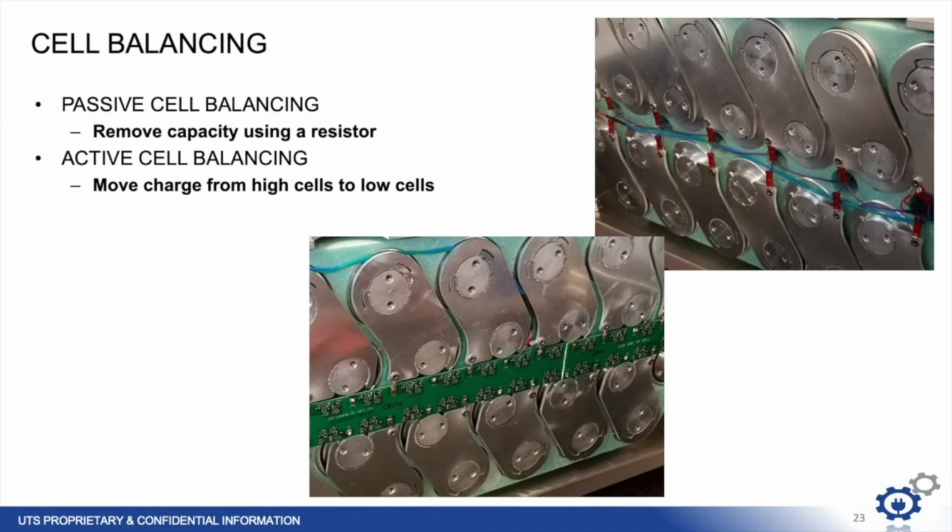One good way to achieve a good electrical balance is to achieve a good thermal distribution. This underlines the importance of the thermal design we just discussed. But what do you do to mitigate the potential variations in cell capacity you're bound to experience from vendors? Well, you implement a balancing methodology.